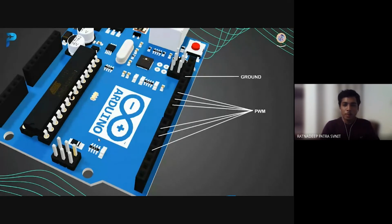Above all these 14 pins, we have a ground pin, and above this we have the AREF pin. AREF just means analog reference. Using this analog reference pin, we can control the input range for the ADC. We mentioned earlier, while discussing the analog pins, that we can manually control the input range for ADCs. So using this AREF pin, we can control the input range.